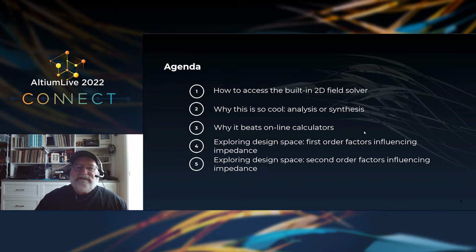And that's the advantage of a 2D field solver, that Uri's tool and many of the other 2D field solvers out there are accurate to better than 1% absolute accuracy. I've done some analysis, others have done analysis, and their accuracy generally is very good. Typically, and we'll see that sometimes some of the online calculators can be pretty good as well, but when you're off from their sweet spot, typically around 50 ohms, it's hard to know how accurate they are. If you're given the chance, you always want to use a 2D field solver to do the estimates of the design for a target impedance.